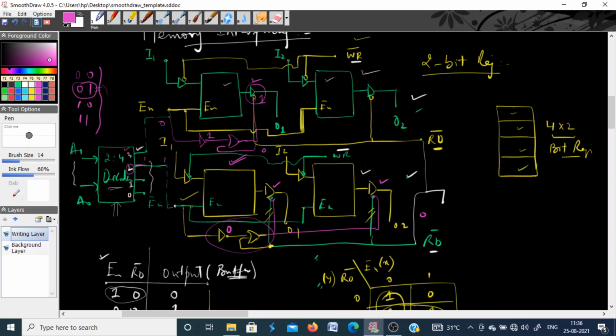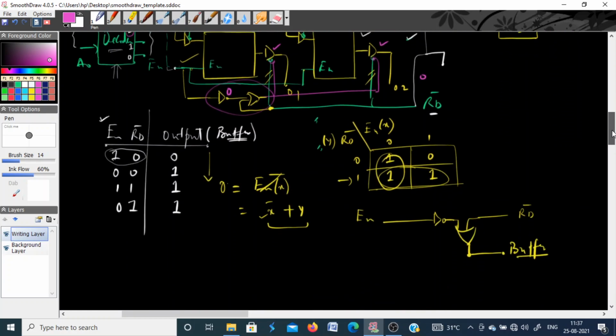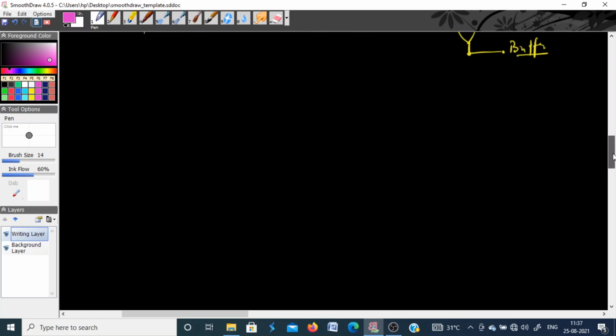Okay, so at a time you can read the information from this register or this register or this register. So this is how now your address decoder is identifying the memory locations. See, although this concept I have not obtained in any books, but when I was going through this, I realized that once you press this read signal, all the buffers, they get activated at the same time, so the data will start flowing from each memory location on the data bus. Okay, so to control this, this is the possible solution. So you may look for some other solutions for this also.